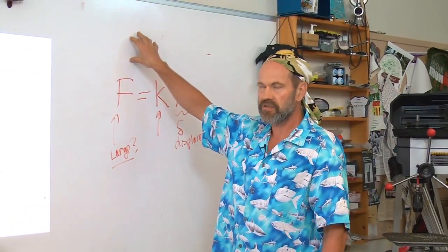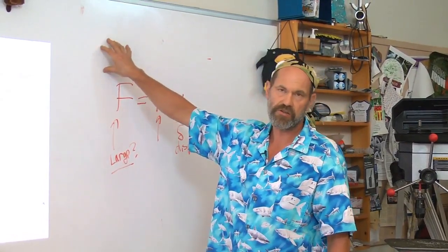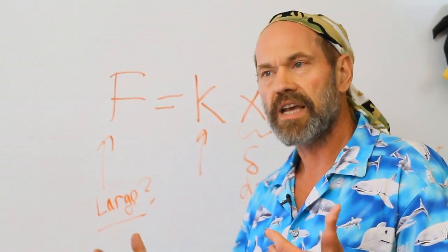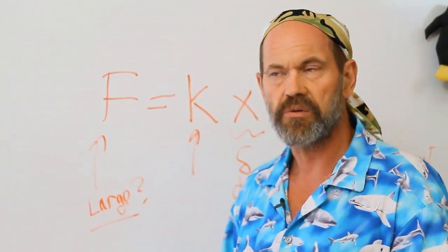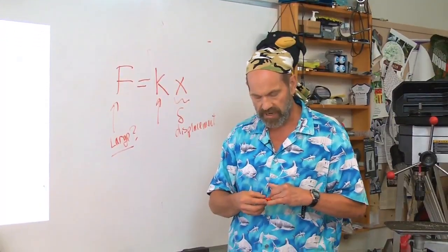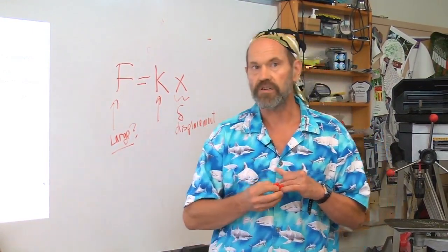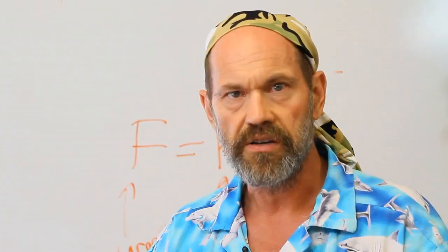Remember, the stress goes like the force to the 1/3. The deflection goes like the force to the 2/3 power. Learn how to use especially the nonlinear relationships so you can combine all kinds of simple machine elements into really neato, cool structures yourself. That's the art of machine design.